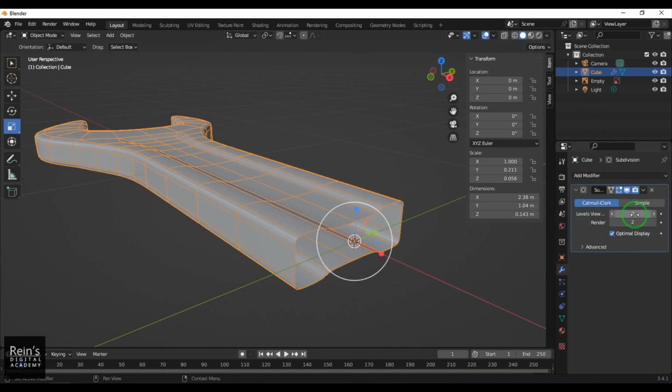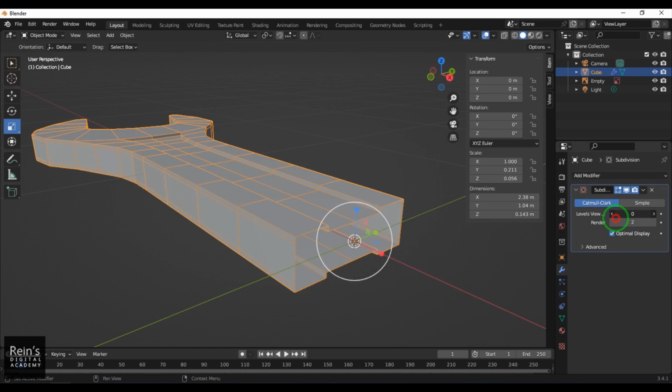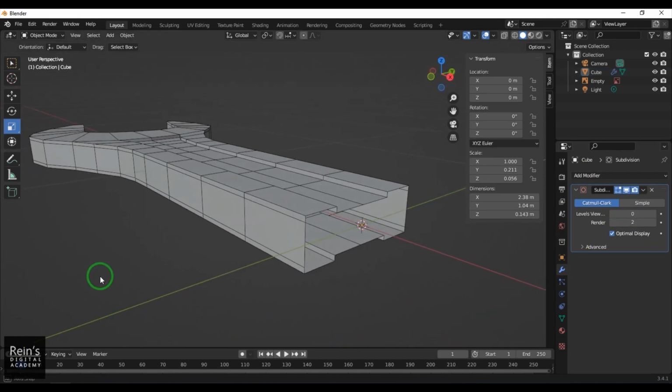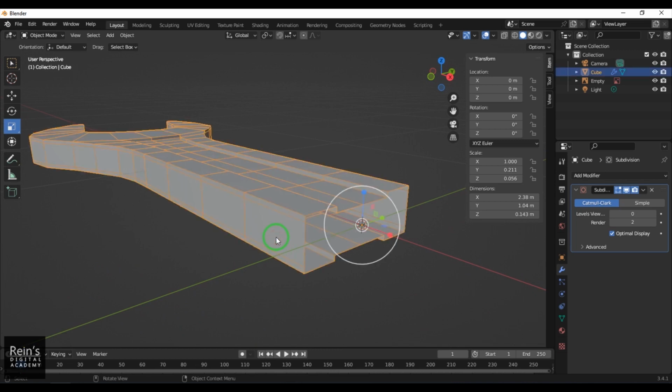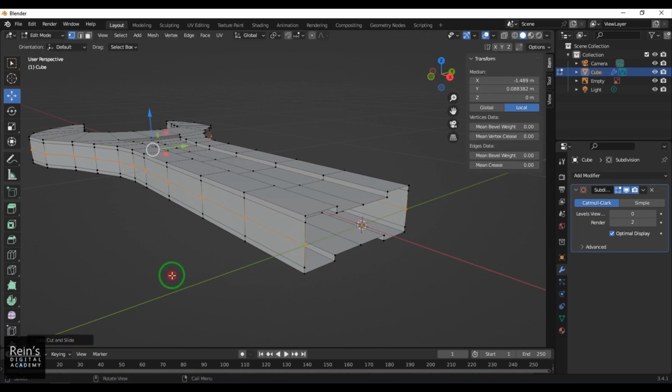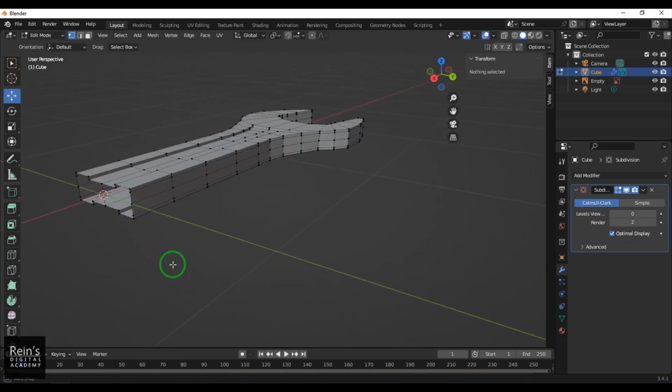If you go to the modifier, I've created this smooth by the shortcut Control 1. It automatically created it. Meanwhile, I select the model, Control R after hitting tab, and then I got a middle line there.